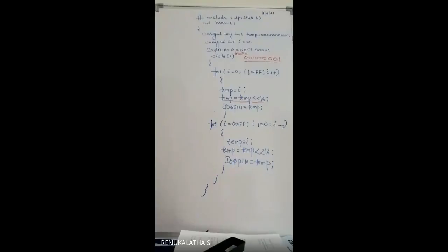It should come to 16th. Very good. Because you see, you are sending the data from which register? To the port IO pin register. Correct. Whatever the memory location data we are assigning here, finally it should go to a register only. From the register, it will go to where? Port only. So now our aim is to send that suitable data to the IO0 PIN register.